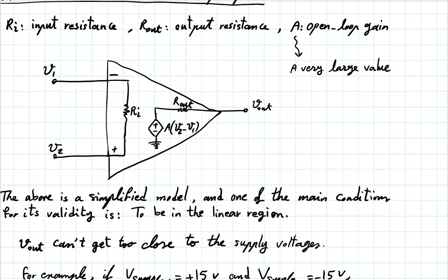Think about, for instance, a voltmeter that you connect between 2 points and you measure the voltage. This is in essence what you're doing, but you're multiplying the voltage with some factor. Well, for a voltmeter, you want a very, very high input resistance, right? In fact, for an ideal voltmeter, you want an infinite input resistance so that there is no current going through.